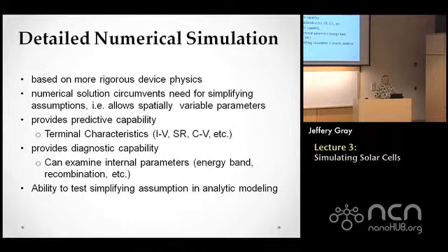We can generate terminal characteristics, which is the predictive capability I mentioned before, and also diagnostic capability, because not only can we generate the external terminal characteristics, we can also take a look at what's going on inside the device. Professor Lundstrom mentioned that he showed you lots and lots of pictures of what was going on inside. That's one of the most powerful features of detailed numerical simulation: it's like taking a microscope and looking inside the device. There's still a lot to be said for analytic models because they're simple to use and give you a little more intuition, but this is a convenient way to make sure that the assumptions you've made are really valid.